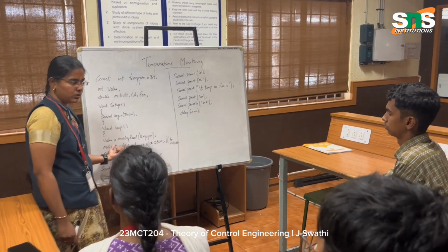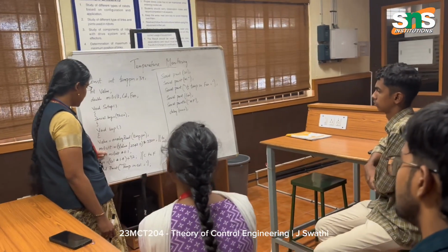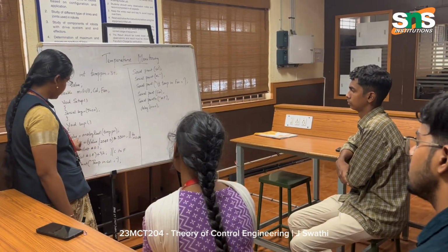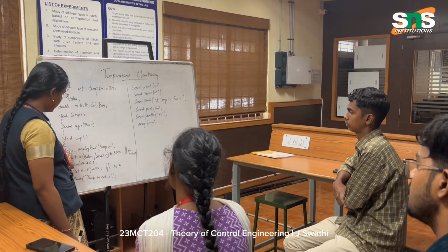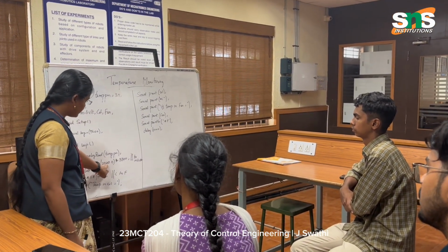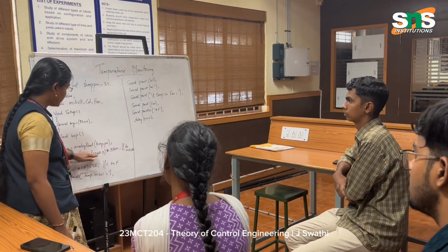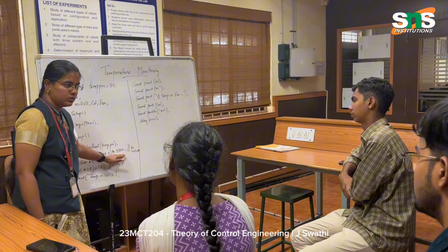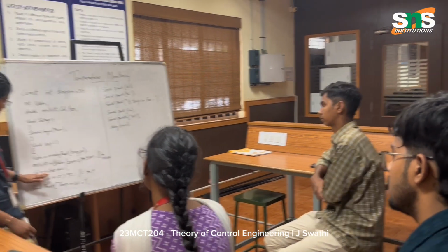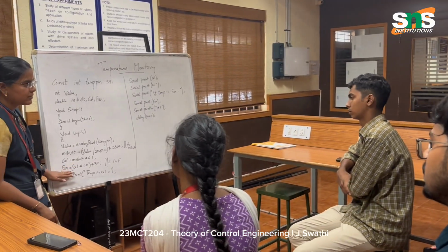That is in millivolts. For the conversion, I am taking this millivolt variable equal to the value, that is the real world value, divided by 2048 times 33,000. So I am going to convert it into millivolts. Next, after that, I have to convert into Celsius and Fahrenheit, right?